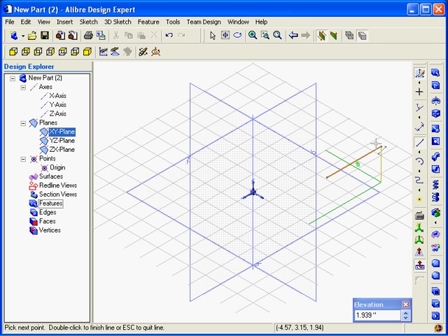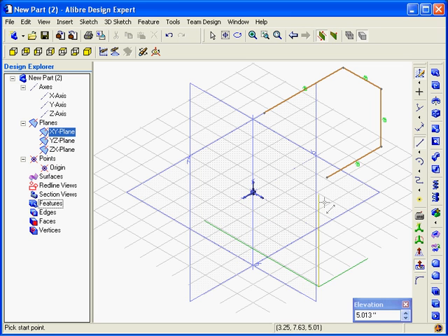And now I will press the E key and hold it down while I am placing the next endpoint. Notice the elevation line rising. I will left-click to place the point and then release the E key. And then I will stay at this elevation to place my final 2 segments. I will close the elevation dialog box by left-clicking the X in the upper corner. This can be done at any time while in 3D Sketch mode.